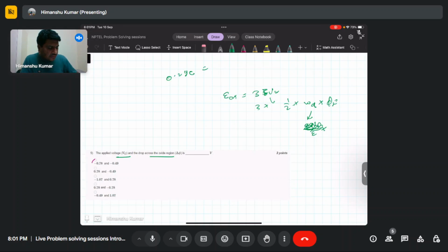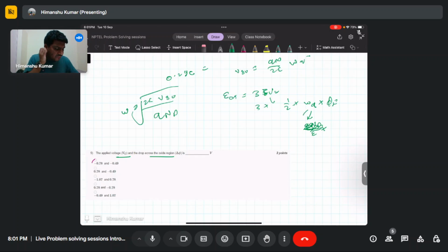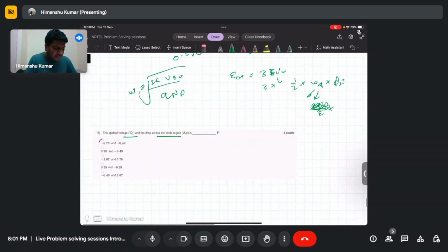And that basically is like the surface potential equal to q nd by 2 epsilon W square. So W you can calculate as the square root of 2 epsilon times the surface potential by q nd. So you can calculate this depletion width. From that you can calculate the electric field, and the field in the oxide region.